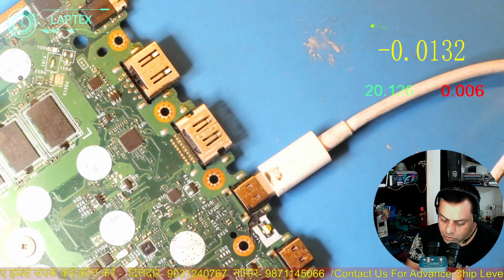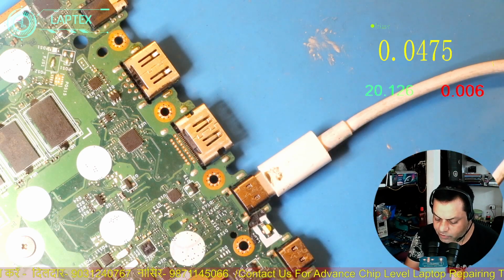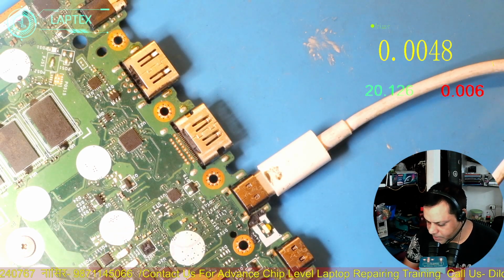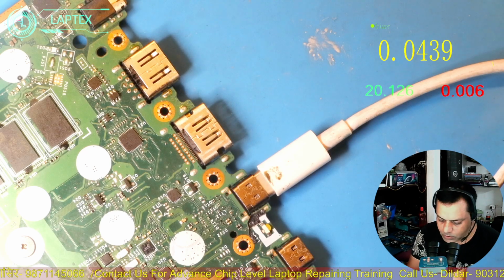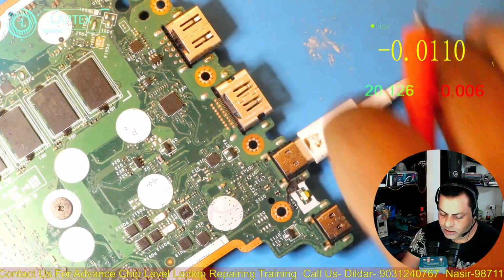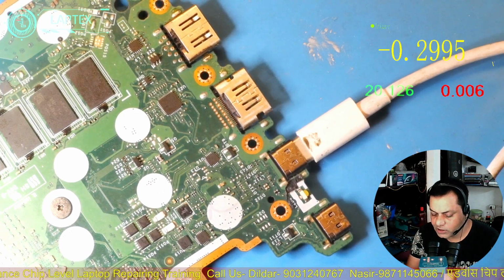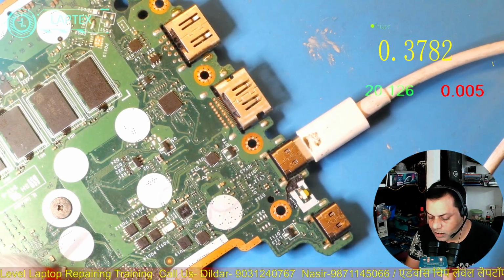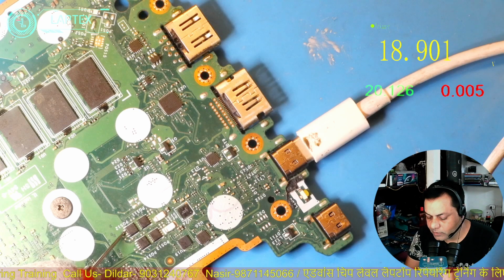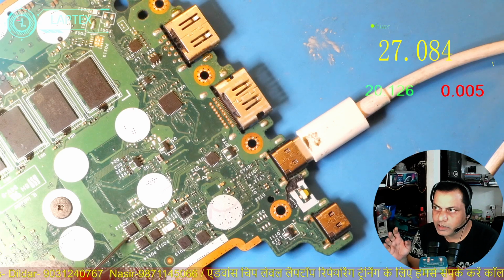Right now I don't know where it is going, and I found that this voltage was missing, so I removed it. Maybe that IC could be alright. Now the scenario is that it is turning on and off, and this is the load it is taking. One question is whether voltage is going out to the MOSFET or not. Now it will be distributed from here. On this side we have got 18 volt. On the gate the high drive is working very well.